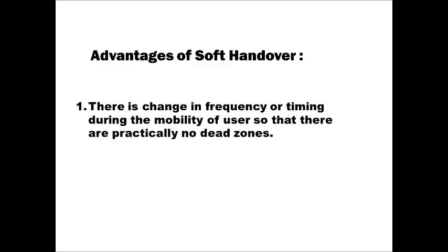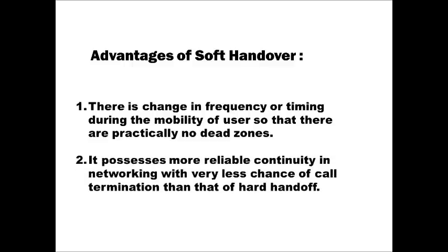Advantages of soft handover are as follows. There is no change in frequency or timing due to the mobility of the user, so that there are practically no dead zones. It possesses more reliable continuity in networking with very less chance of call termination than that of hard handoff.